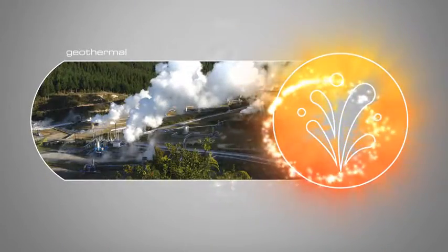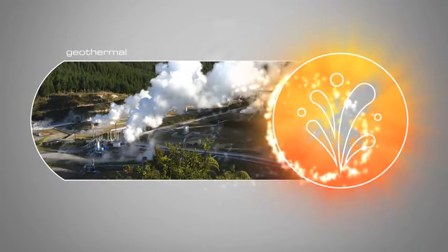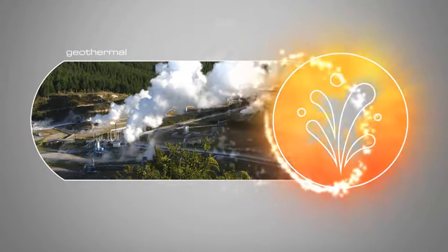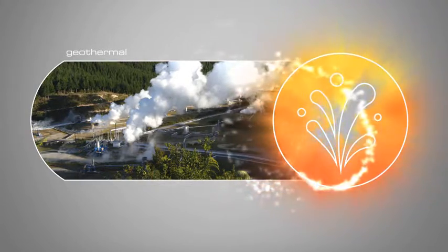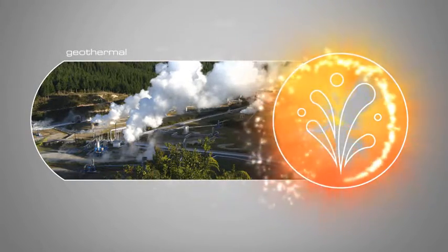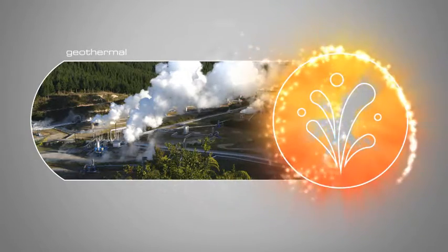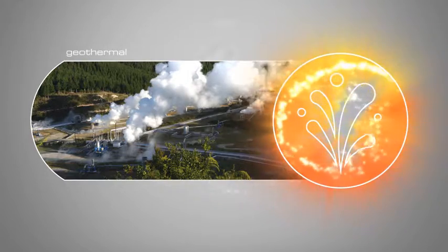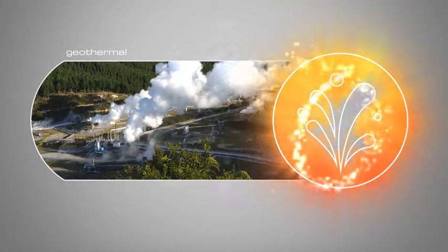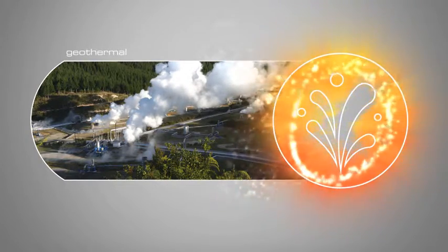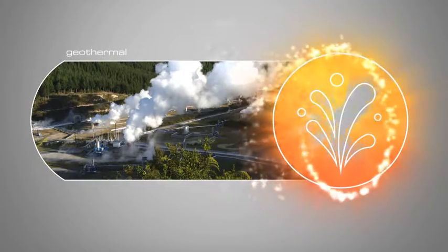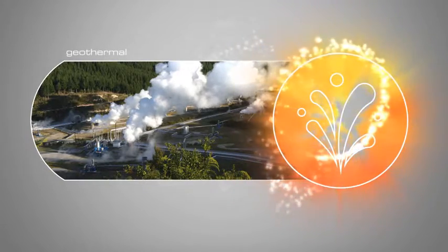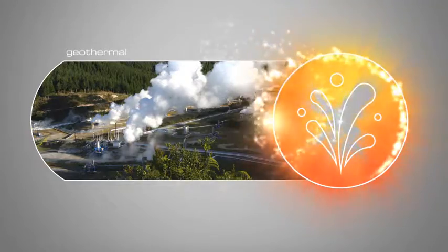Geothermal electric plants were traditionally built exclusively on the edges of tectonic plates where high-temperature geothermal resources are available near the surface. The development of binary cycle power plants and improvements in drilling and extraction technology enable enhanced geothermal systems over a much greater geographical range. There are three basic types of electric power plants: dry steam, flash steam, and binary cycle.